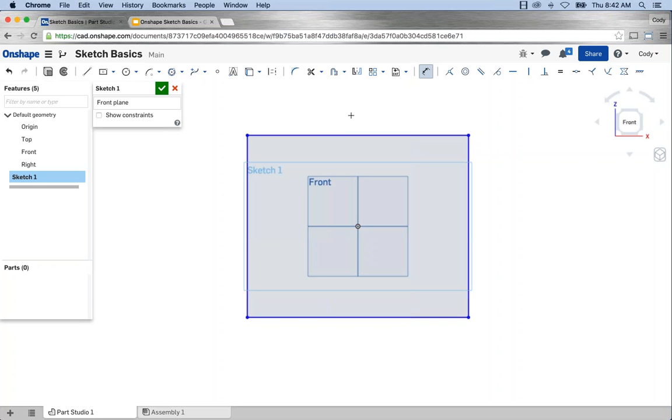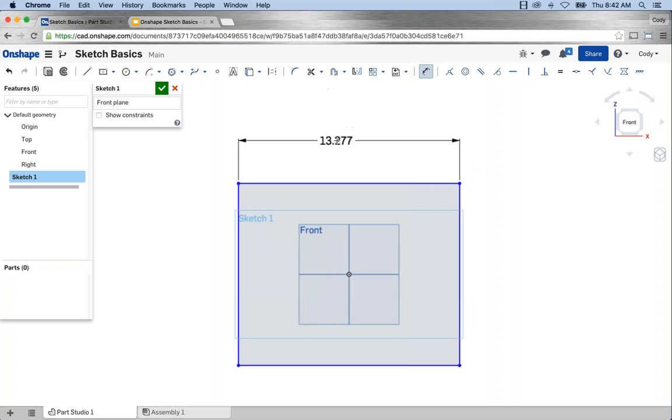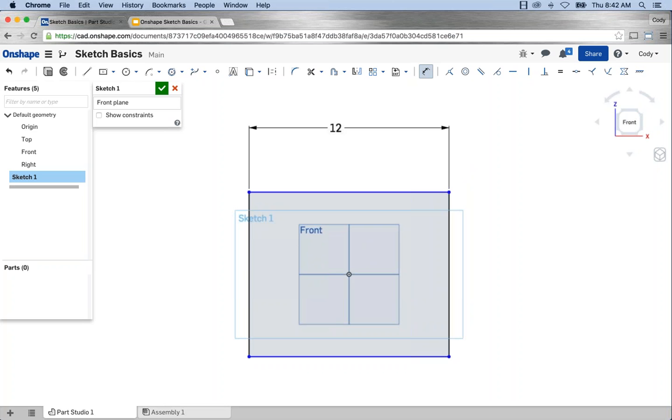Now, in this case, if I select a line, just left click, move my cursor up, an important step, move the dimension away from the sketch geometry, then left click again to place the dimension. You'll see a little window appears. You punch in a size, 1/12. Okay. So now the entire sketch scales to that first dimension. Right, so you'll see everything kind of zooms out just a bit. The entire sketch scaled to that first dimension, but now the width of this is actually defined by a dimension.